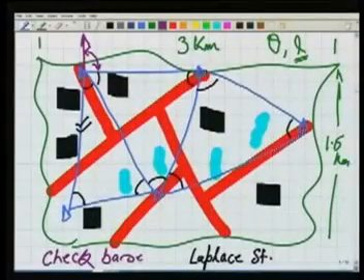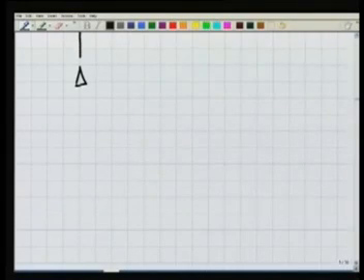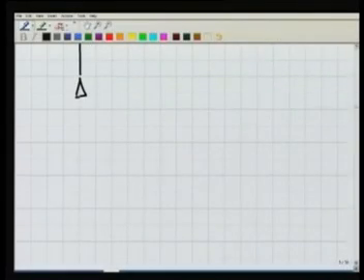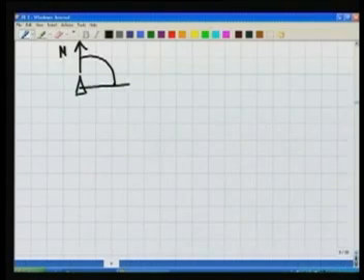Well, in order to plot this traverse, how will we begin? We will start from our very first point, the point which was on the top. I know the direction of the north here. I know the bearing of my one line, and by computation I know the length of the line. So I plot this. Then I know the internal angles.